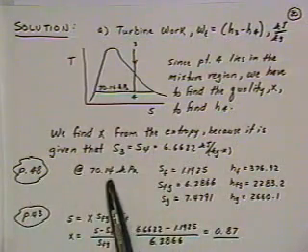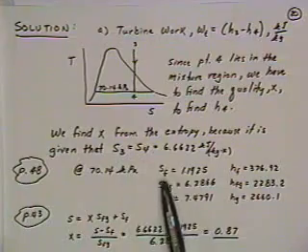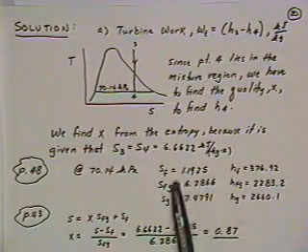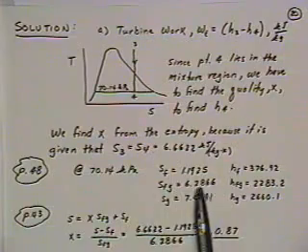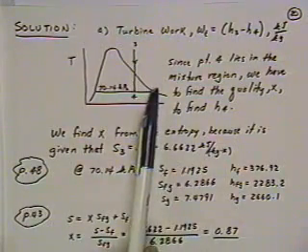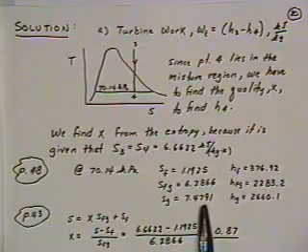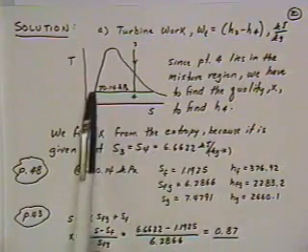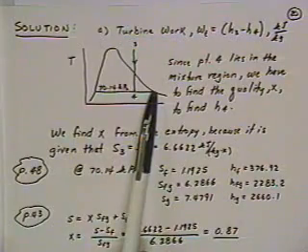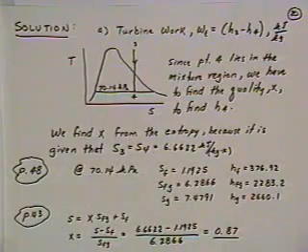So page 48 on the tables, at the pressure value of 70.14 kilopascals, we look up and find SF, which is the entropy at the saturated conditions, 1.1925, SFG 6.2866, SG, which is the entropy corresponding to the saturated vapor condition, is 7.4791. Similarly, HF is 376.92, HG is 2660.1, and so HFG, which is HG minus HF, is 2283.2.